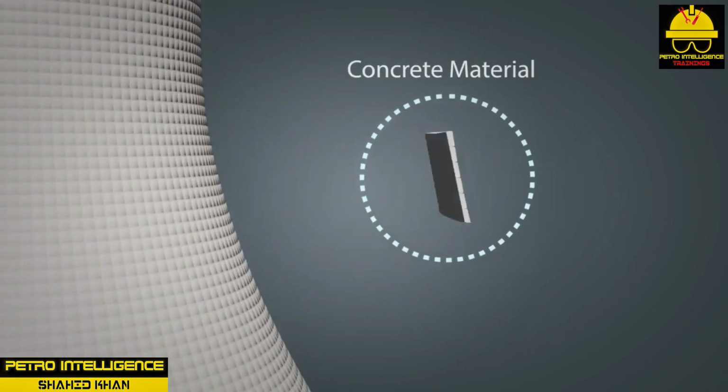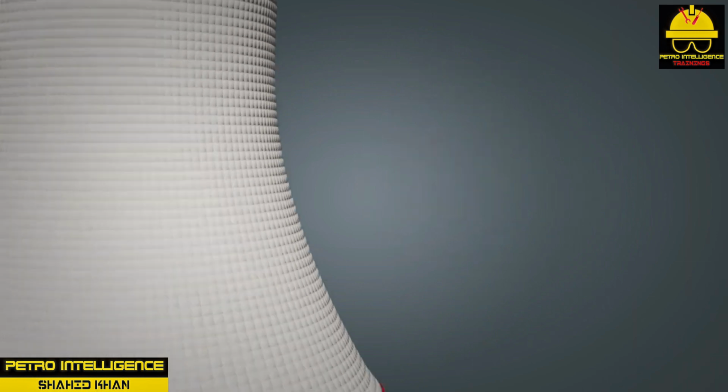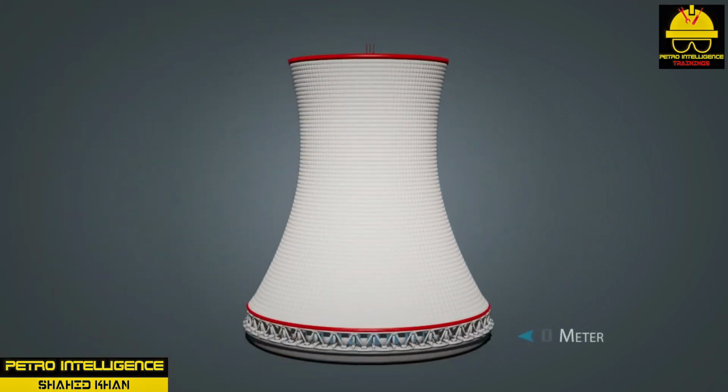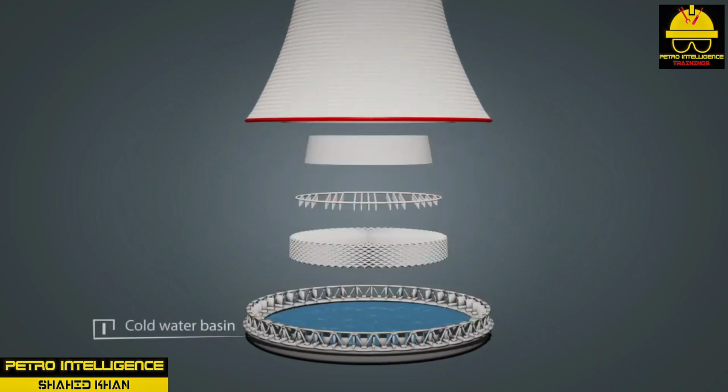A cooling tower contains wood or plastic slats, called fill, that direct airflow and the flow of water falling from the top of the tower. The downward flowing water coats the fill and forms a film, thereby increasing the surface area for contact between the cool air and hot water. Hot water transfers heat to the cooler air it contacts in the tower.